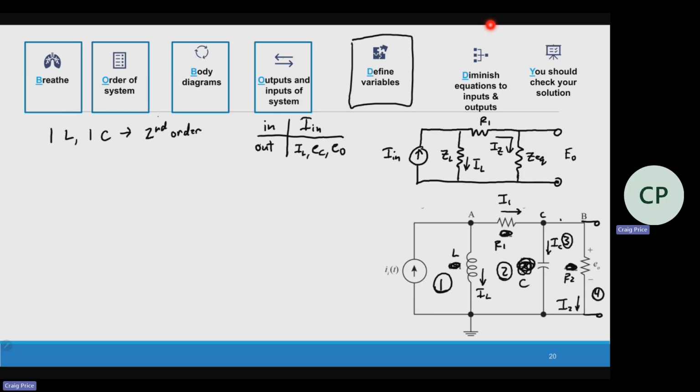These kind of drawings. So now it's going to your definitions. Either I'm using impedance: for an inductor, it's L times S. Capacitor is 1 over CS. Those are the impedances that we can use. Resistor is just R. Or if you don't want to go that route, okay, let's look at the loops. Let's do some KVLs. Let's do some KCL. Let's get all these equations going and the equations on the equation sheet so we can then solve.